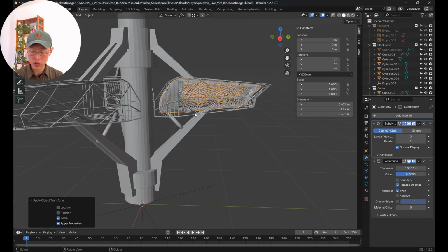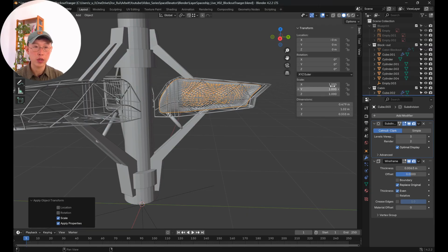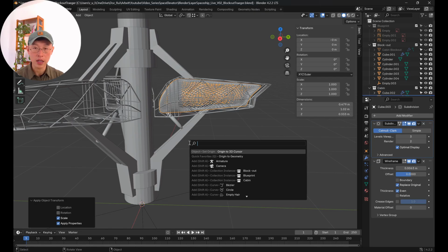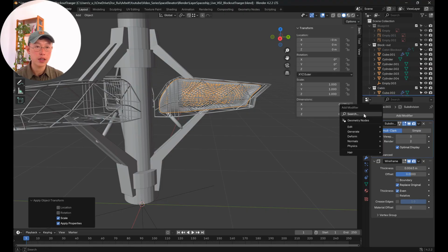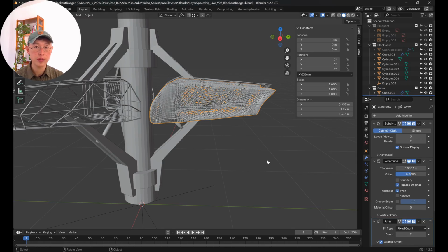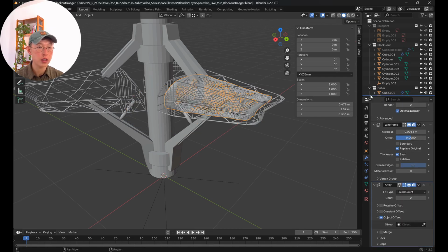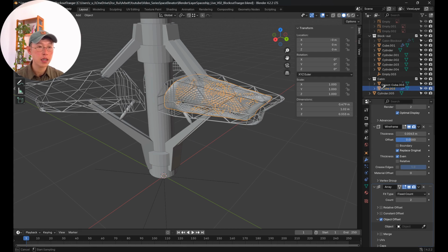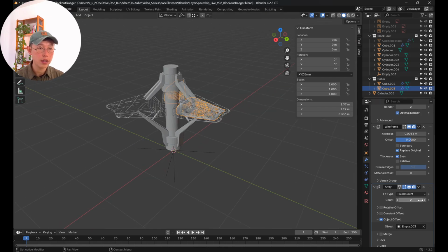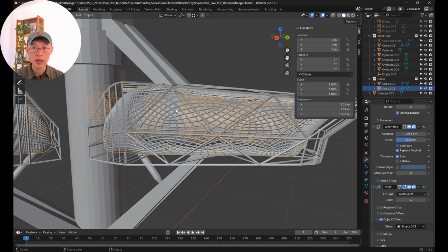So the same steps like before. First, click Control A to change the scale value to 1. And I want to have the origin at the position of the rotation axis. And then I'm gonna add an array modifier. It's just repetition. And we don't have relative offsets. We have object offsets. And click on the empty and number 3. And the inner cabin would be the same.